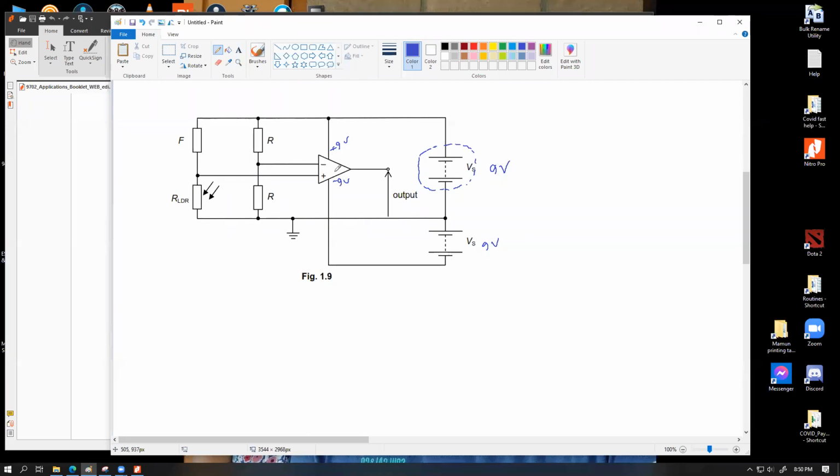Now let me tear this apart piece by piece. Try to understand. Whenever we do operational amplifier calculations, it is very important that you give a plus sign in front of plus voltages and a minus sign in front of minus voltages. It is highly recommended. In some of the mark schemes, positive voltages are not given with a plus sign, or maybe they have given plus in a bracket, showing that it's optional. But I highly recommend that you learn to write all of your voltages with the individual signs. It's very important.